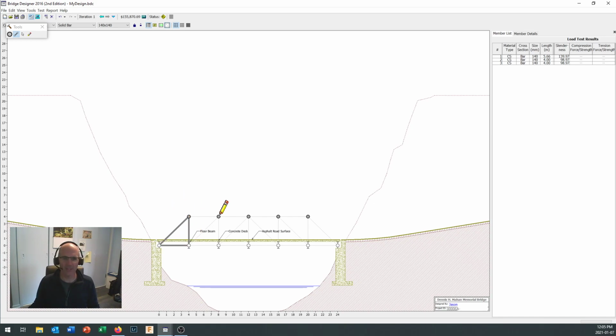If you try to design something like this with a square or a rectangle in here, chances are that's not going to work for you, because these two nodes right here can pivot and become a parallelogram with these two nodes over here. There's nothing keeping this member from rotating about this node. That's why you need to put a cross brace right across here. Now that you've cross braced that, you've got two triangles braced together so it can't pivot in there.